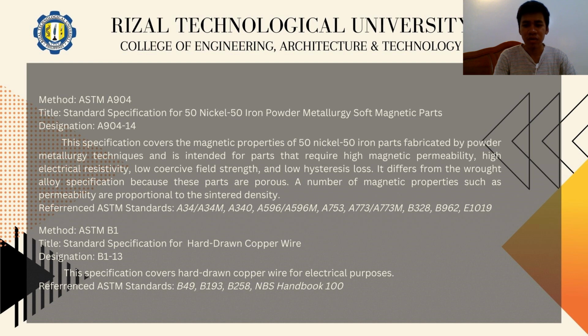The user and producer shall agree upon a representative number of specimens for testing. Should the sintered parts be subjected to any secondary operation that causes mechanical strain, such as machining or sizing, they should be resintered or annealed. Next is ASTM B1, Standard Specification for Hard-Drawn Copper Wire.